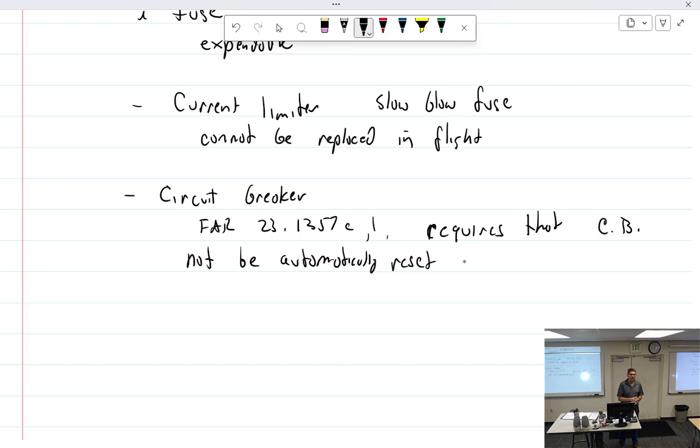So a circuit breaker, as some of you are seeing in lab now, comes in two different types, really. Type 1 has a little collar where you can pull and pop them out. Type 2, they're flush, and you can't pull them out. They'll pop on their own, and you can push it in, but you can't pull it. I don't like those. I like the kind where, as a pilot, if I need to shut something down, I can reach over, pop it right out. I've got my autopilot with auto trim, which has had problems with runaway nose over. I know exactly which circuit breaker by feel is right there in front of me. It's the first one there. Pop that one and the next one, I'm good. So I like to be able to pull those.